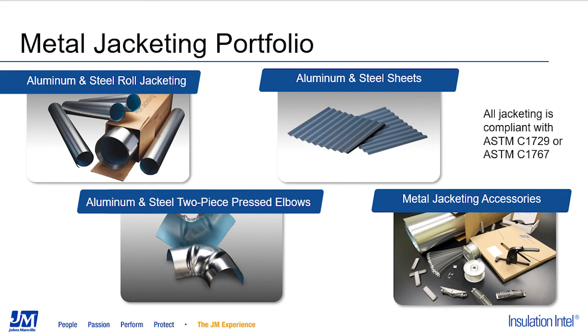I'm also not going to go into the details, but all of our metal jacketing meets the applicable ASTM requirements contained in the metal jacketing standards C1729 and C1767, as well as the applicable metal alloy standards such as B209 for aluminum.